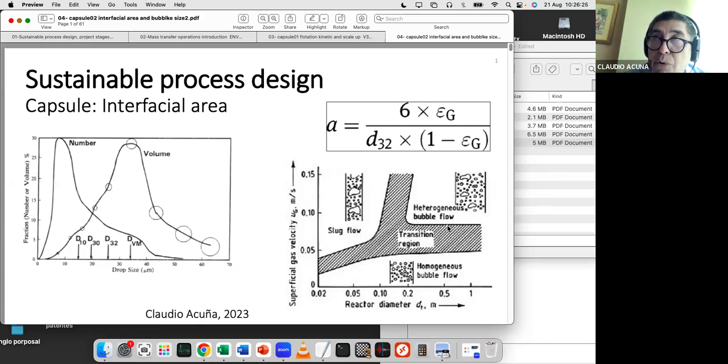For example, if you are dissolving big crystals, the kinetics of this dissolution is going to be completely different if you have 1 micron crystals. If you compare 10 micron crystals, the curve will be completely different, because in this case it will be a shrinking core model, you know.